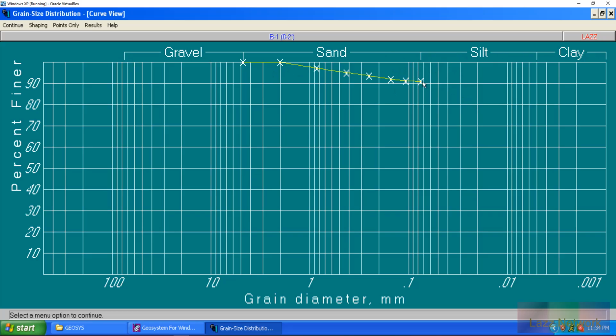So technically this is the material that's passing your 200, which typically speaking, when you do a sieve analysis, most of the time, well, I can tell you already, if they want a 200 on it, all of the time you will wash it. You will never do a sieve analysis on material that needs a 200 sieve and not wash it.